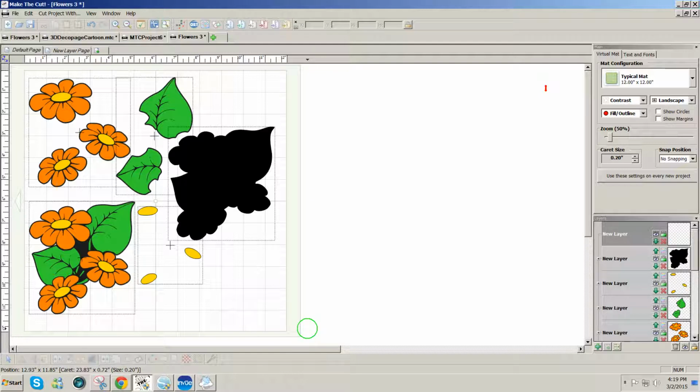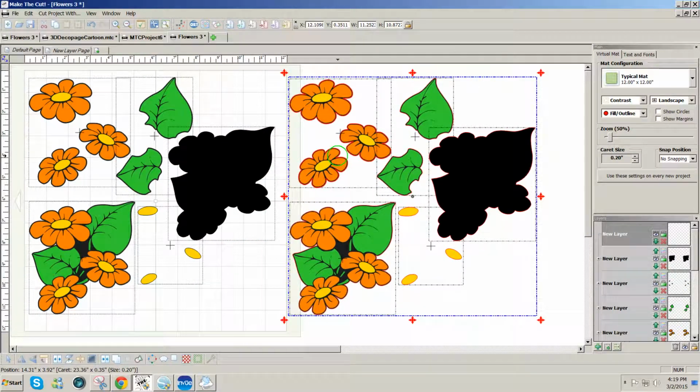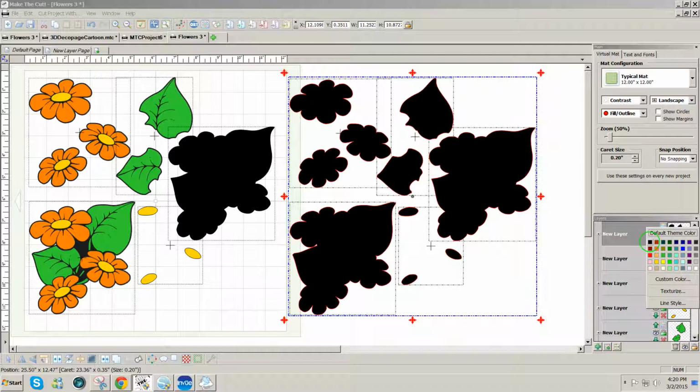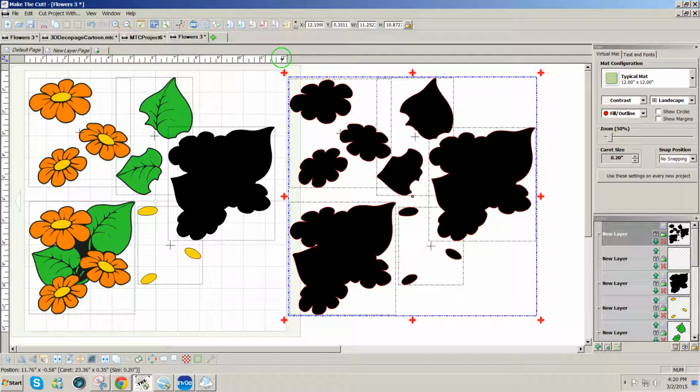So let's prepare for one other inevitability, and that is if the software you're taking it to does not want to trace your design, your picture image cleanly. To prepare for that, we're going to select everything, hold Control Shift and drag, and on this one we're just going to black it out. We'll send it to its own layer by clicking on the smaller of the two green plus icons, and then on the color box on that top layer where we just sent this, we're going to select black. Because the pictures will not transfer with it anyway, we're going to export this as an SVG.